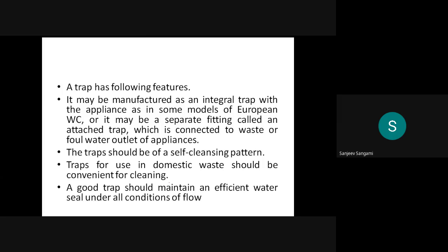The trap should be of a self-cleansing pattern. Traps for use in domestic waste should be convenient for cleaning. A good trap should maintain an efficient water seal under all conditions of flow. So the first one is the gully trap.